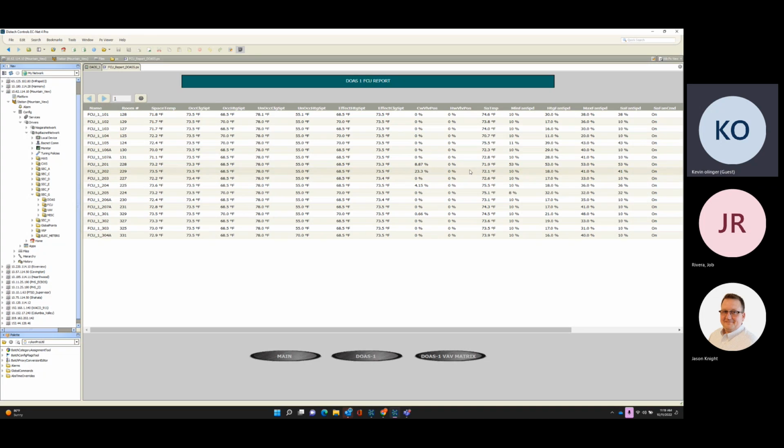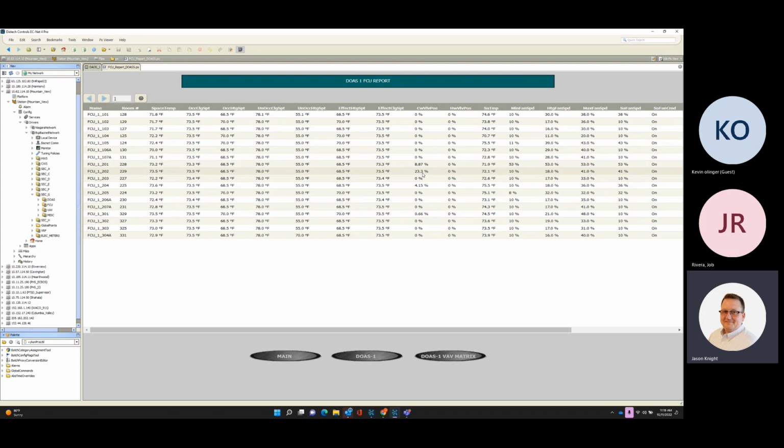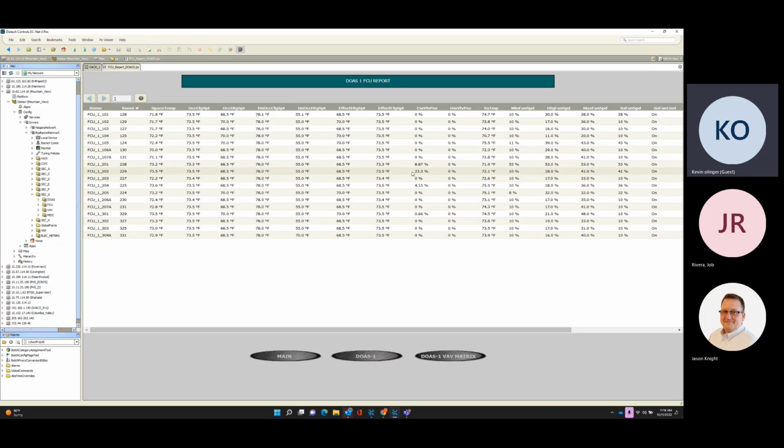When you say the algorithm is running more aggressive, you're talking about more or less the PID loop tuning for the zone control. Is that a fair statement? Yes, the proportional, integral, and derivative. Obviously, we don't use derivative in HVAC control, but the proportional gain is significantly set faster in G and H.